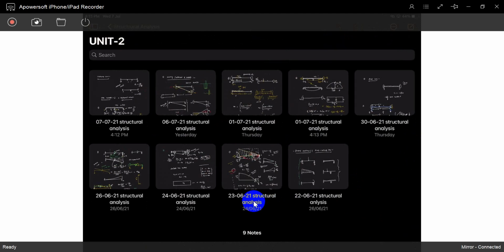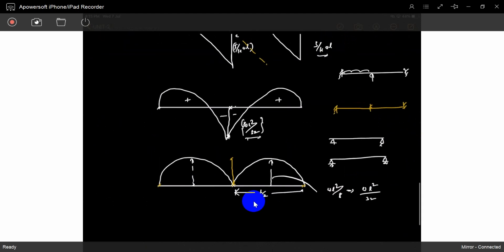Just the representation has small changes. So like this, today also the same thing. So you can write it. AB is taken as free ends, CB is also taken as free ends. And now if everything is taken as a fixed joint, A has a fixed end moment of 0 because it is a hinge joint. B is also 0 moment, but C has WL square by 32 as a hogging moment. So now you can add fixed end moments.